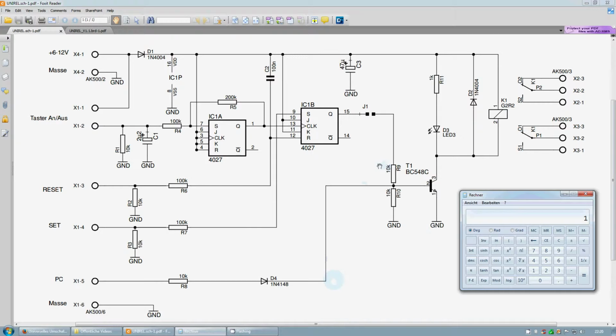You can imagine it as if this resistor here is now in parallel, because when this is low it's connected to ground, and we have R9 and R10 in parallel, which gives us 5K to ground, and this will have nearly no effect on the current through R8 and the necessary base current to switch transistor T1 to the on state.